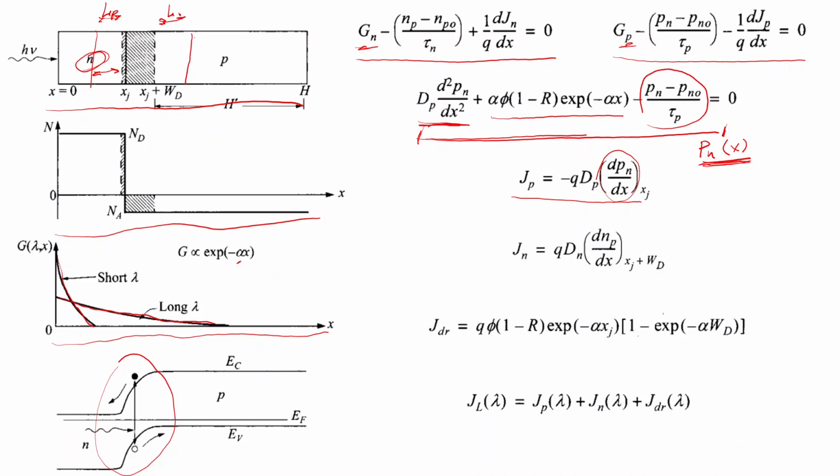So that is the diffusion current of minority non-equilibrium photogenerated holes. The same we can do also for the diffusion current of minority electrons in the p-type region. I don't put explicit equations here because they are quite bulky, so you can take a look in the textbook. This gives the whole solution. We just need to understand how we come to this point.